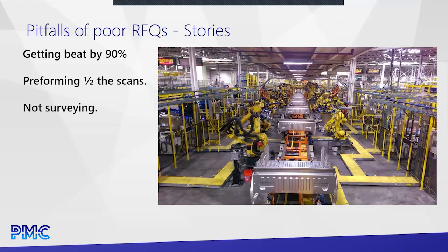This is even more critical in mobile scanning. So in terrestrial scanning, unless it's catastrophically bad, you can almost always get something that sort of works. Maybe you can get it to plus minus 6 inches, which is maybe good enough to as-built a building. If you screw up mobile scanning, it cannot be fixed. It can be off by multiple feet, and there's no way to fix it.